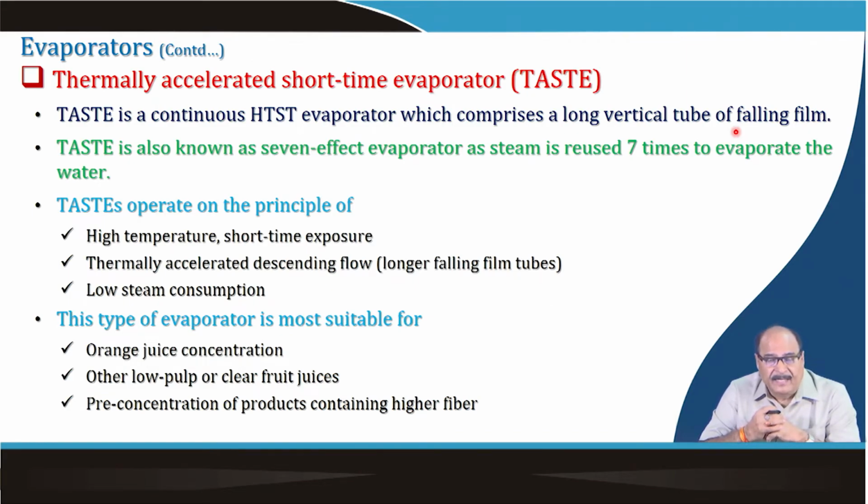Then the thermally accelerated short time evaporator, which is commonly known as TASTE. TASTE is a continuous evaporator which comprises long vertical tubes with a falling film. TASTE is also known as a multiple effect evaporator, as steam is reused multiple times to evaporate the water.